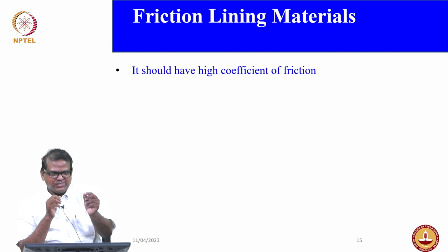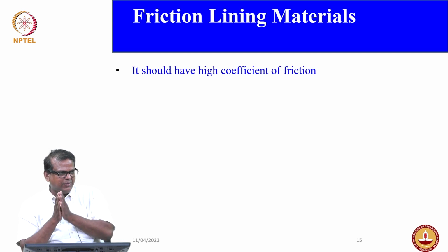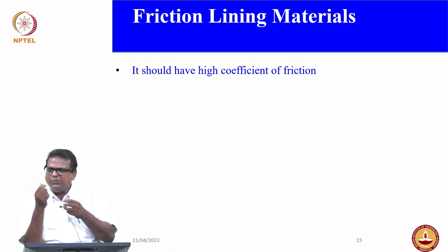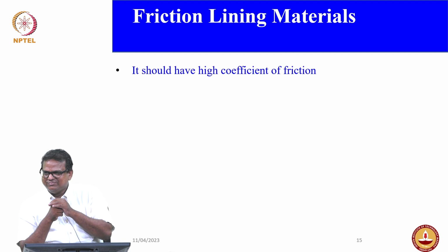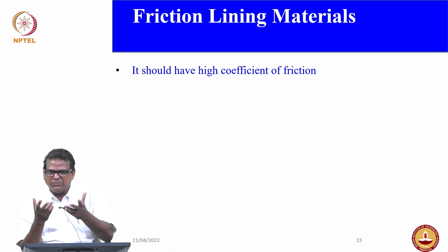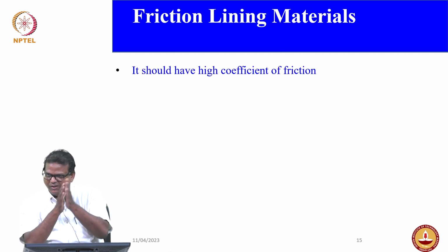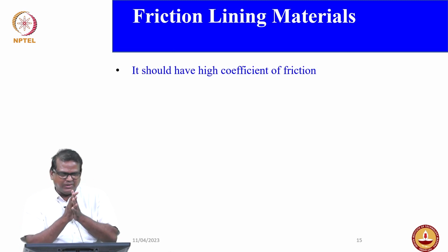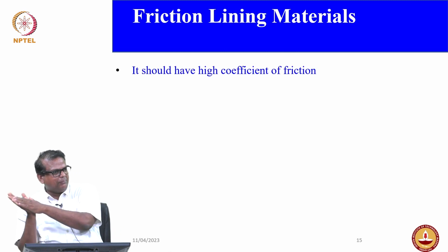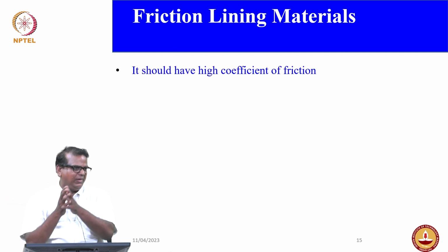Remember, the friction lining comes into the picture only during clutch operation. What will be the duration? Only a few seconds, right? Engage and disengage, maybe 2 or 3 seconds. Only that time you need to use the friction lining, whereas for a brake you have to stop the entire vehicle.